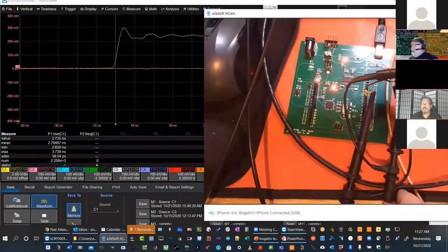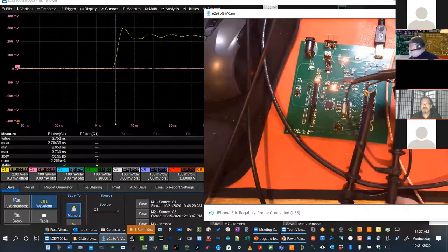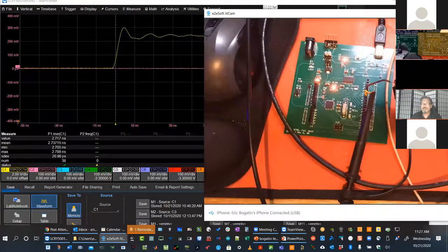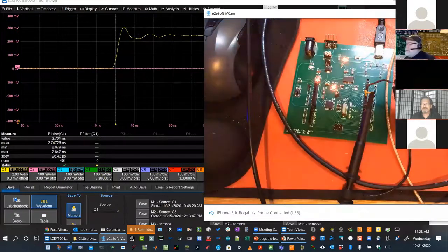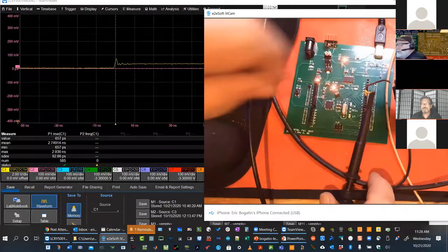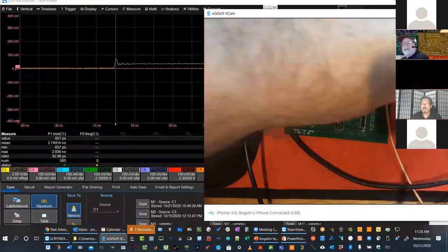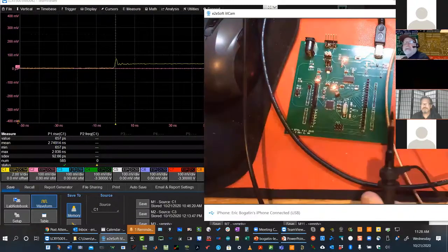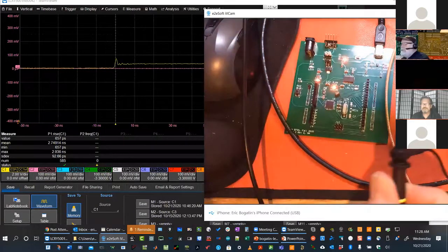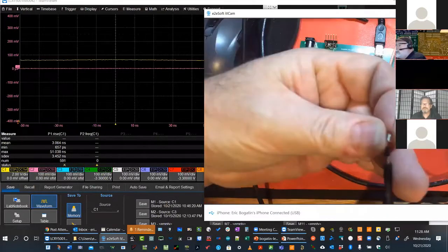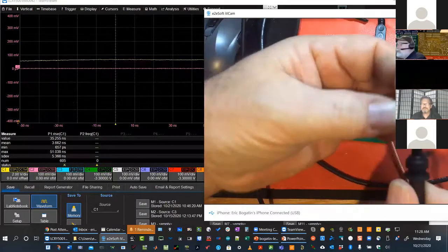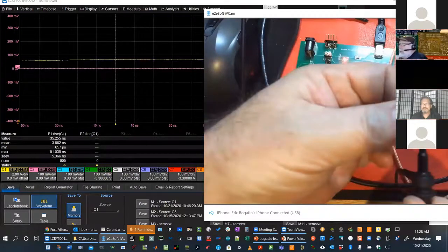And that's why every 10x probe ships with these tiny little spring ground tips, so that we can make a very low inductance connection to the tip. There it is, a little spring tip. I'm going to connect this in and show you what that signal looks like when we do it that way. The 10x probe's caps pull off, and when they do, you can see a little shield here. This is the ground connection. Here's the signal pin, and we literally just wind that little spring around, make contact, and now we can probe.